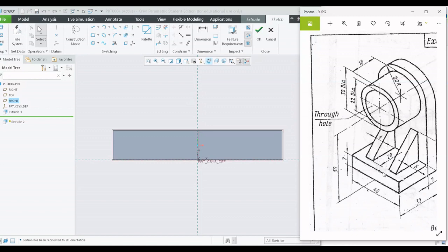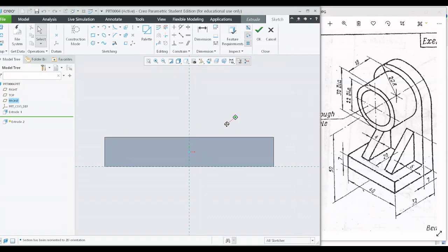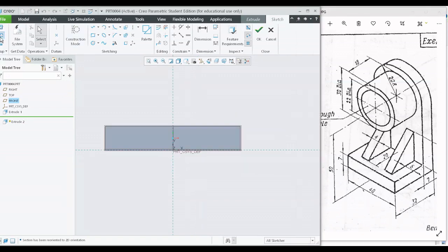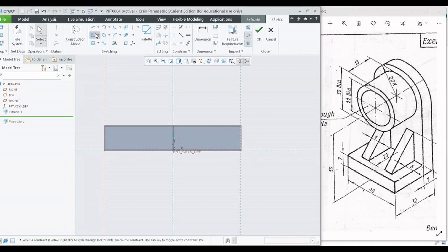So I have to create the vertical wall from the base itself. So this thickness is included in the vertical wall. I mean the distance 50 units is including the 7 unit thickness. So let me create a reference point. It is a good practice to create referencing.